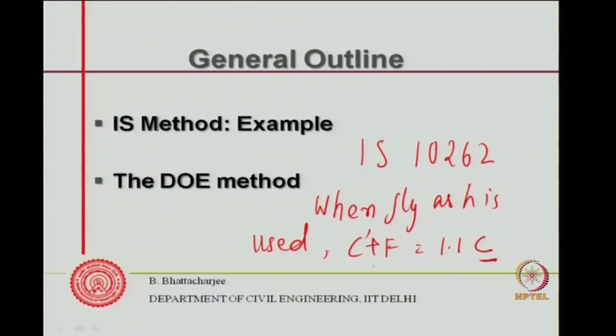If you are using fly ash, increase that cement content by 10%, and that must be the sum of the cement plus fly ash content. So, if you know F divided by C dash plus F, we have decided, let us say, to use 20% fly ash in the system. Then from these two equations you can find out the fly ash and the cement content itself. One is that you increase the total by 10%, so 1.1 C.